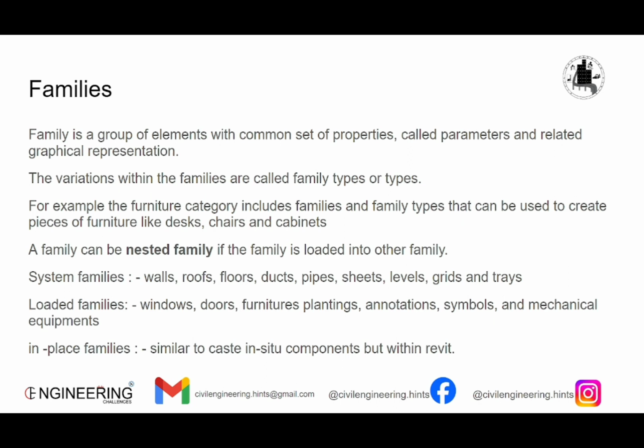A family can be a nested family. In such cases, a family is loaded inside a family. Like I gave the example of a dining table. In this case, a dining table can be made by a desk, a table, and chairs, where chairs and tables can be nested families within the family.